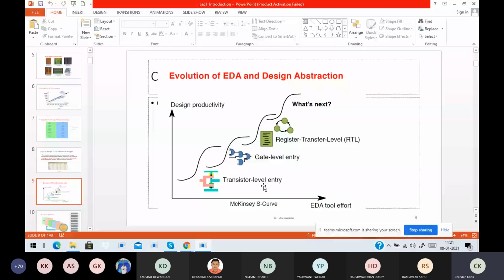Cycle accurate in the sense that every clock the design is actually performing correctly, right? So cycle accurate performance evaluation, even with 10 million, 20 million lines of code at the RTL level, becomes too much, right? So we need more abstraction, and that is where our course comes into play. I'm going to make another level of jump from RTL to C, or a higher level.